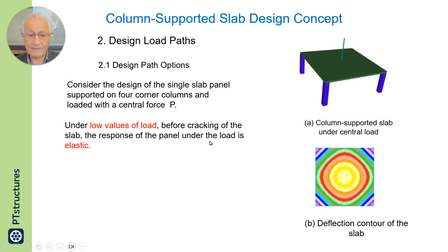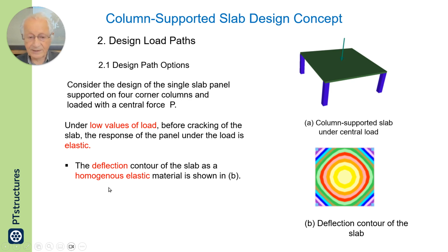at the center. Under low values of load before cracking of the slab, the response of the panel on the load is elastic response. The elastic response will have some deflection shape like what I have shown at the bottom right.